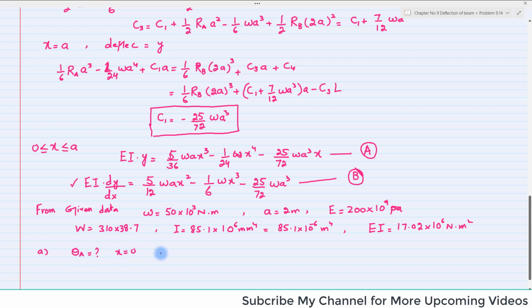Clear? So in part A, it was given to find the slope at point A, which is at x equal to 0. So put all the values in equation B. Clear? When you put x equal to 0, this term will be 0, this will be 0, and this will be theta A. So the EI value is 17.02 into 10 raised to power 6, and dy by dx is equal to theta A.